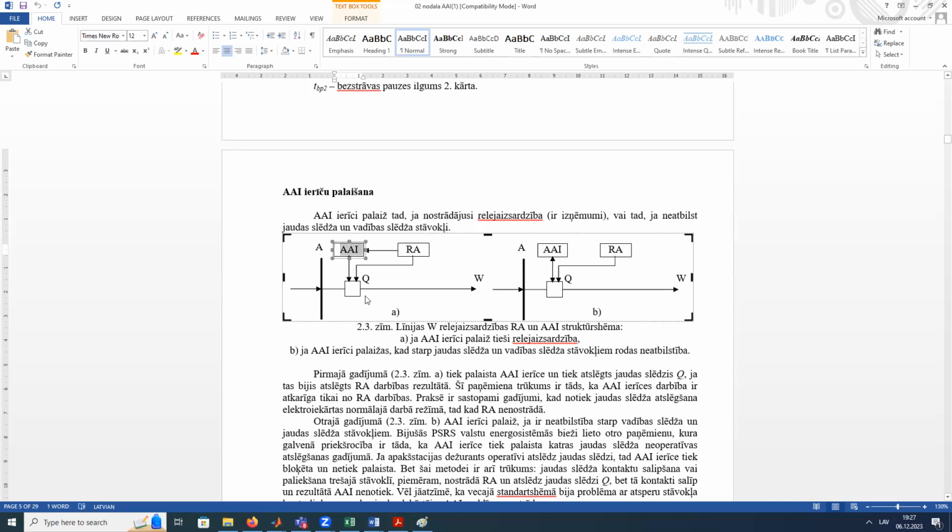So, to be sure that after the disconnection all the air deionization will go, because you understand, if you have a high voltage, the disconnection with a high current is quite complicated, because we have these lightnings and so on. So this is quite difficult for the breaker, and we need some time to wait to be sure that this breaker is ready to operate next. That's why we tell the reclosing to be ready to connect it back, and in some time that is set for this automation, it gives a command to the breaker, please connect the line again.